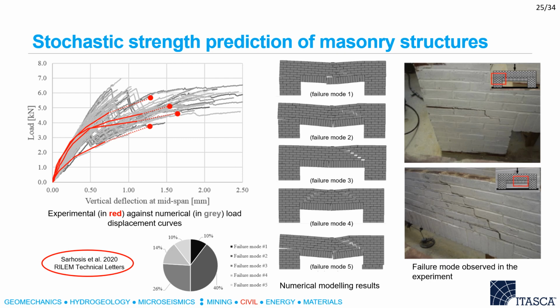The failure mode of the masonry wall panel has also been investigated and compared with experimental findings. Both experimental and computational results showed that there were 4 notable aspects of mechanical behavior in the masonry wall panel, namely, first, initial flexural cracking in the soffit of the panel. Secondly, development of flexural cracks in the base joint of each support. Third, propagation of diagonal step cracks at mid-depth. Finally, fourth, collapse as a result of what is usually referred to as shear failure or excessive diagonal tension.